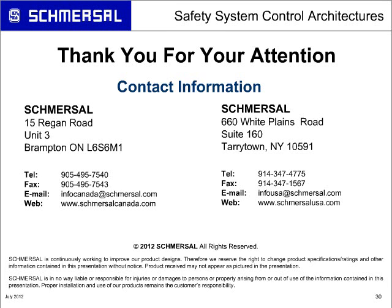The odds are of having two mechanical keys or two cam mechanisms failing at the same exact time, and at the moment that you open up that door, you have a mechanical key break and a cam failure at the same exact time you open up the door. Not saying it's not possible, it's not very probable. The odds of that happening are astronomical. So what happens is if the first switch, the key breaks off, the second switch, the key is still maintained on the door, opens up and rotates those cams to give you an open circuit.